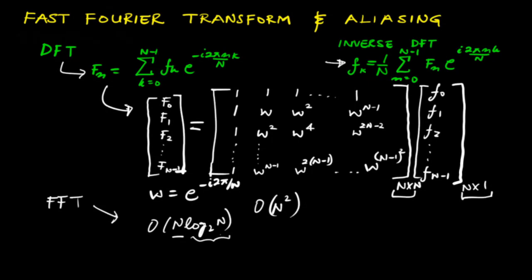Note that FFT is just an algorithm to compute the DFT. However, because of the widespread use of FFT, it is common to hear that we had a signal and we computed its FFT, although what we do strictly is to compute the DFT using the FFT algorithm. FFT in its most basic form requires samples which are powers of 2. So let's say n is a power of 2, let's say 2 raised to power m. Although algorithms exist and there are ways you can compute FFT for other values of n, let's stick to n which are just powers of 2.